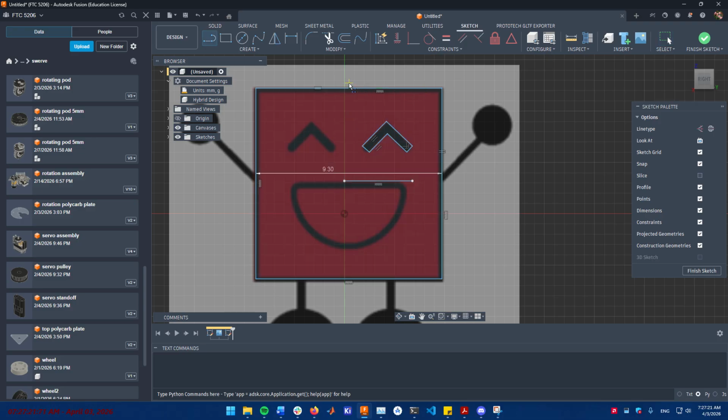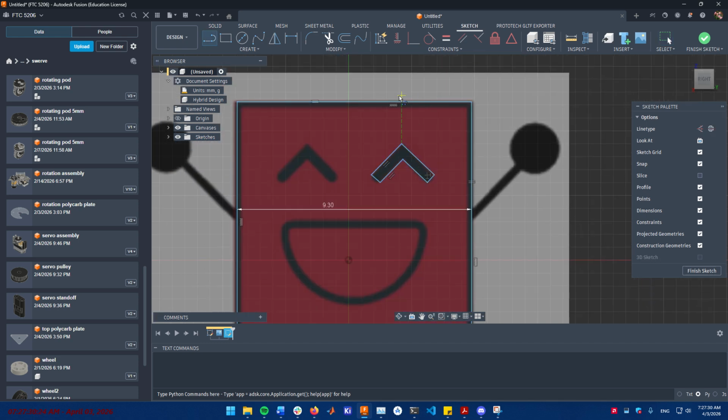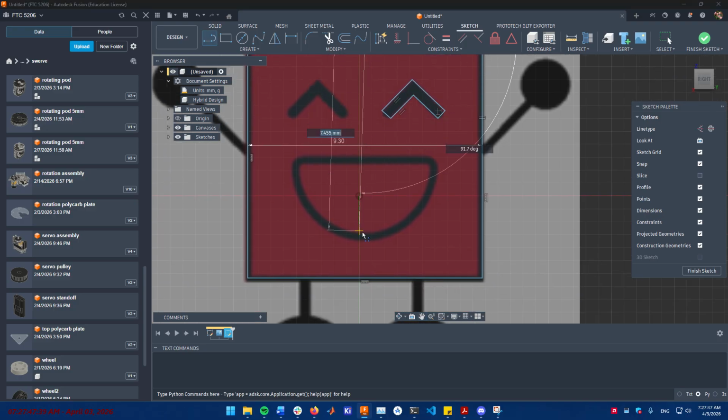We should place a point that represents the midline. To do this, we press the line button, and you can see when I mouse over the middle point, it gets stuck and shows this triangle symbol. That means you've reached a midpoint, and it auto constrains to be a midpoint.